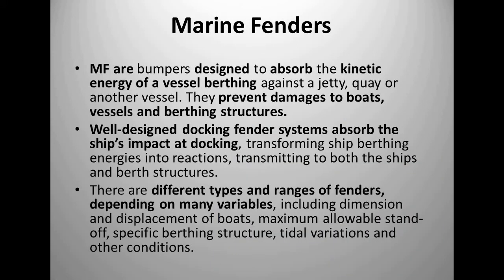And what are fenders? Marine fenders, otherwise called bumpers, are designed to absorb the kinetic energy of a vessel, that is, a ship berthing against a jetty, quay or another vessel. They prevent damage to both vessels and berthing structures. A well-defined docking fender system absorbs the ship's impact at docking, transforming ship berthing energies into reactions transmitted to both the ship and the berth structures. There are different types and ranges of fenders depending on many variables.